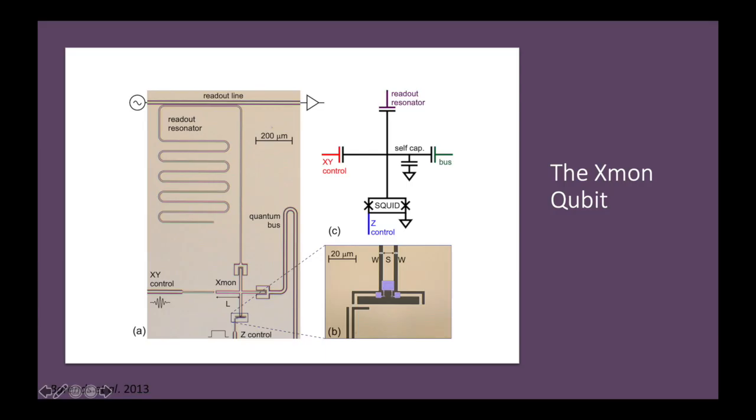So the Xmon qubit gets its name because of its crossbar structure. The primary innovation of the Xmon is really in the scalability and very easily tunable design. So instead of coupling through an optical resonator, it couples with other Xmon qubits via direct capacitors sharing a common ground. So the XY control, readout, and coupling mechanism, the bus, are all mediated by capacitors. The most important thing here is that the Xmon, the three-arm capacitor coupling method, enables fast control and a scalable fabrication process that sets the stage for the realization of linear arrays of Xmon qubit processors.